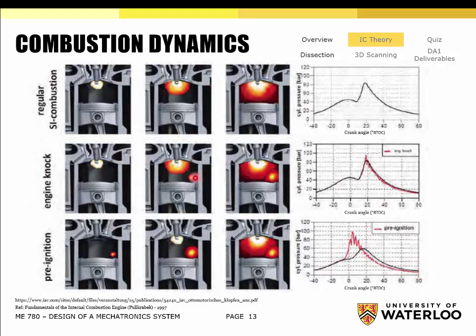And then just because there was some dirt in the cylinder, or locally there was a hot spot, it reignited here, and that causes two competing combustion events, and they fight with one another, and what they produce is this red response here that's very erratic and jagged.